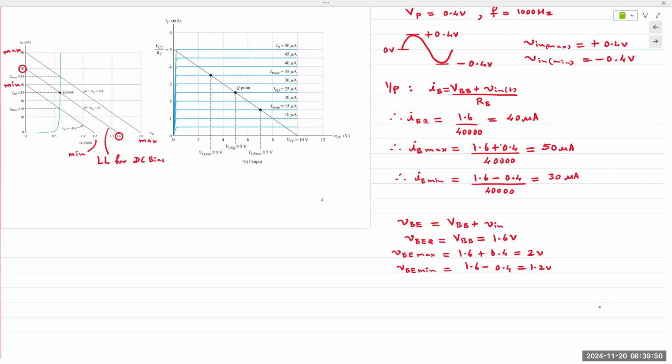And so we have 2 more load lines, and our input signal is varying between these load lines. And the intersection points of these load lines, right here and right here, give us the 3 Q points for our input side. Okay.